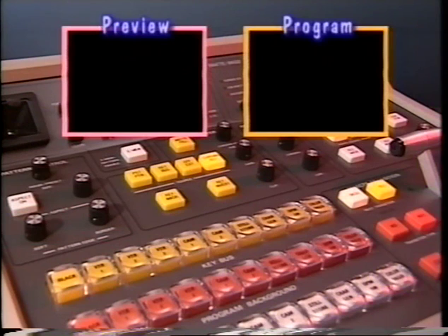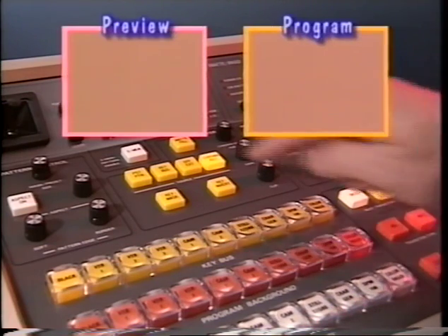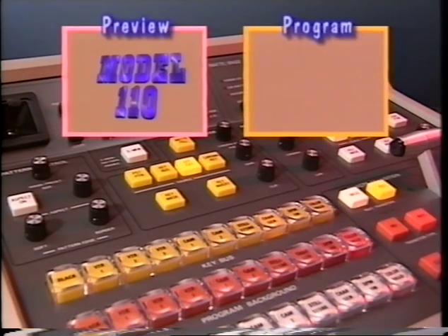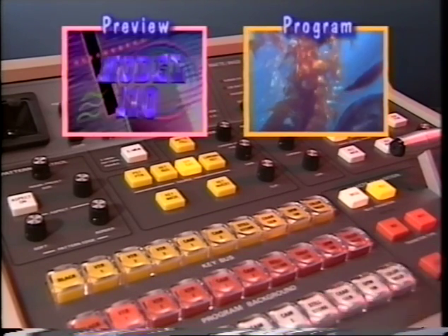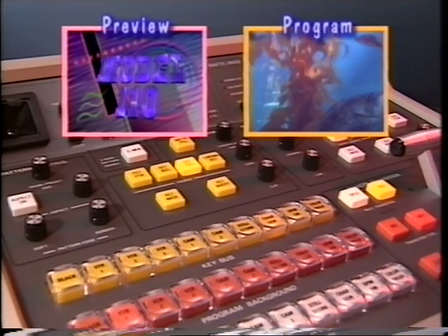First, the luminance key. 3 signals must be selected to create a luminance key: a background source, a key source, and a fill source. The background is either selected on the program background and/or a new source on the preset background bus.